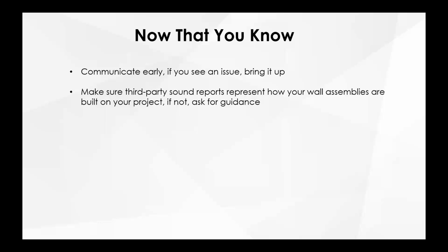Make sure the third-party sound reports represent how your wall assemblies are being built. If it's not, ask for guidance. Again, they give you a third-party sound report, and it's showing a 1.25 inch track used at the head of wall, and your studs are screwed to that track. You can't build it that way. Bring that up so everybody's on the same page. Ask for guidance.